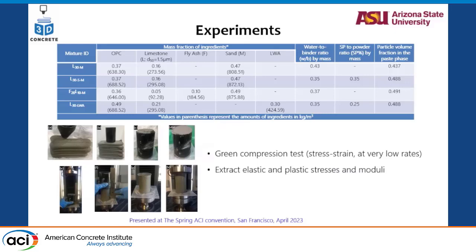a 2x4 cylinder using a steel pipe, and then we tested these cylinders for uniaxial response. One particular thing that was required for us was, if there was not a proper preparation of the material, you will miss the first initial elastic response because it's a very small response regime. So making sure that the top surface was flat and the whole surface was in contact with the loading platen, so that the elastic response does not mix with the plastic response, was necessary. For that, we used the L scale to make sure it's perpendicular. We made sure the top surface is flat such that the whole loading platen will sit on the